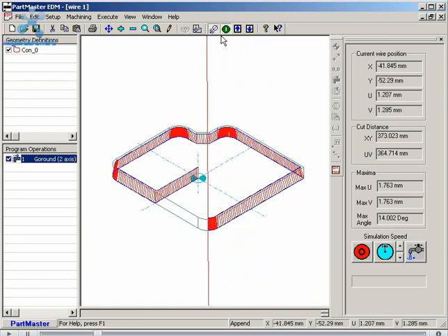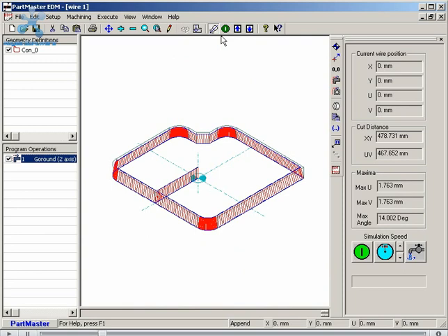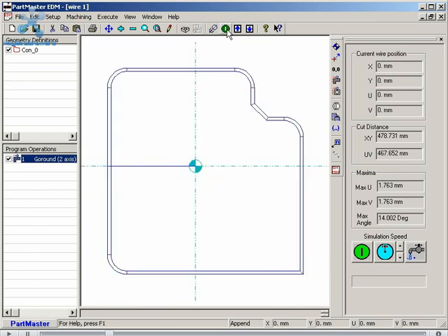And in its simplest form, when we post-process that, then we would get a basically 2-axis shape but with taper angles. If we go back to the plan view, what we can also do is, using what we call notes, we can add instructions to various positions around that shape. So let's say, for instance, that along this top edge here we want the wire taper angle to change from 10 degrees to a different value.